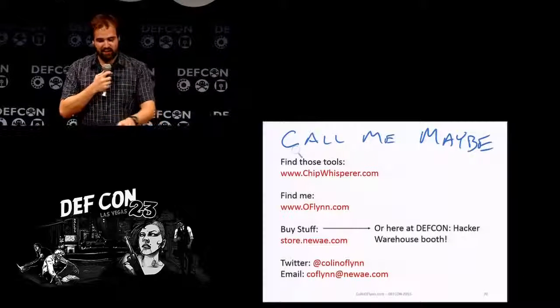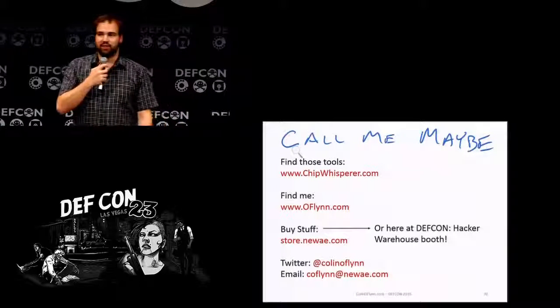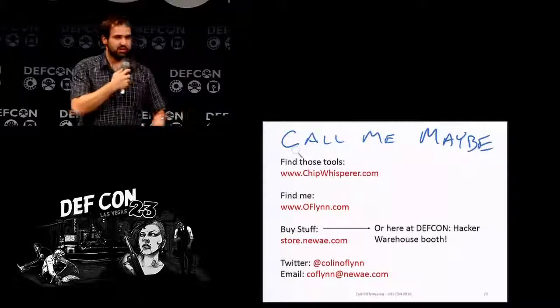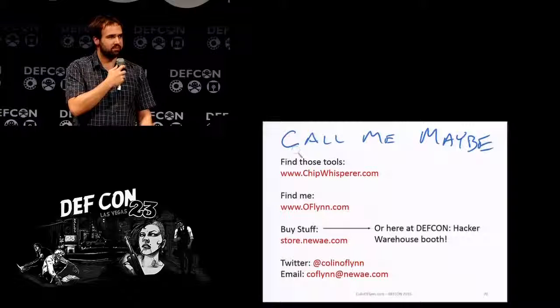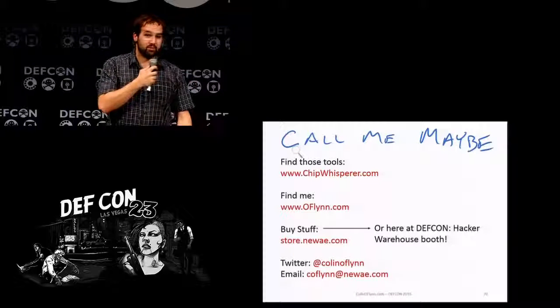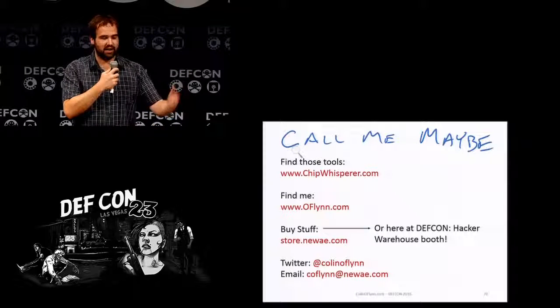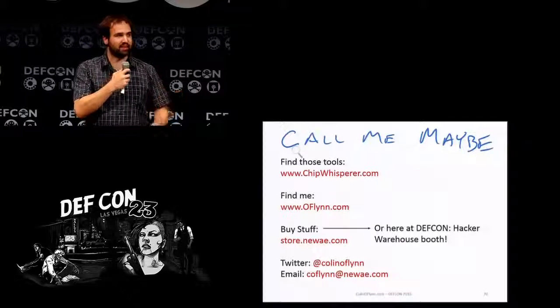Besides anything public, like that Atmel device, the XMEGA has a hardware AES engine. It's been published to be breakable. There's a number of products that people have published these results on. The keyless entry, a key fob for a car, was a popular one. The side channel analysis was able to break it. So there has been a number of real products, and all the smart card hacking stuff from pay TV. Some of that was side channel, not that much of it actually.